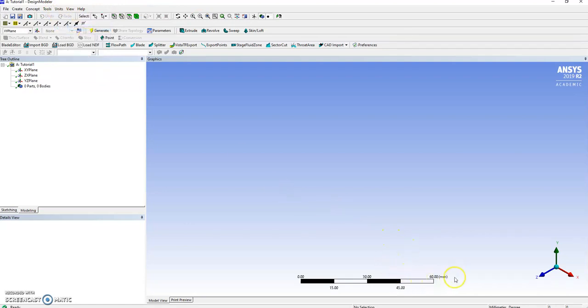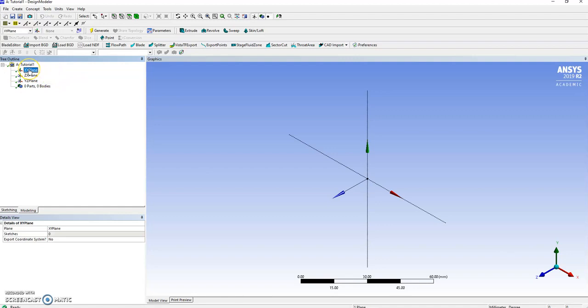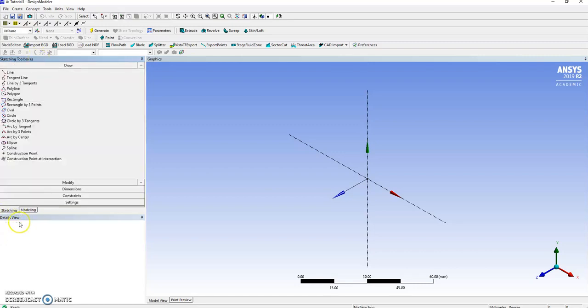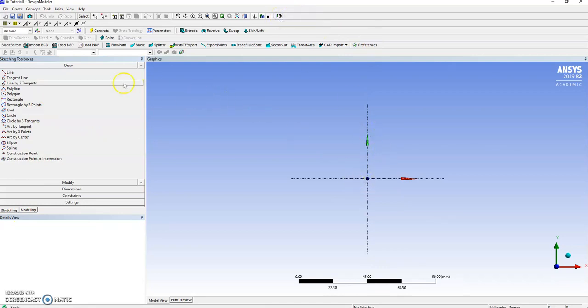Okay, different. And next we want to sketch, because in order to make parts, you need to create sketches and apply features to these sketches and so on. So how do you do that? Well, you choose a plane, and you can generate planes, but here we're going to use a basic one, the XY plane. Click on it, and automatically go into the sketching tab here, and that's it, you're going to sketch. I like sketching flat, so I choose that look at face, and that's it. And I can then create my shapes.